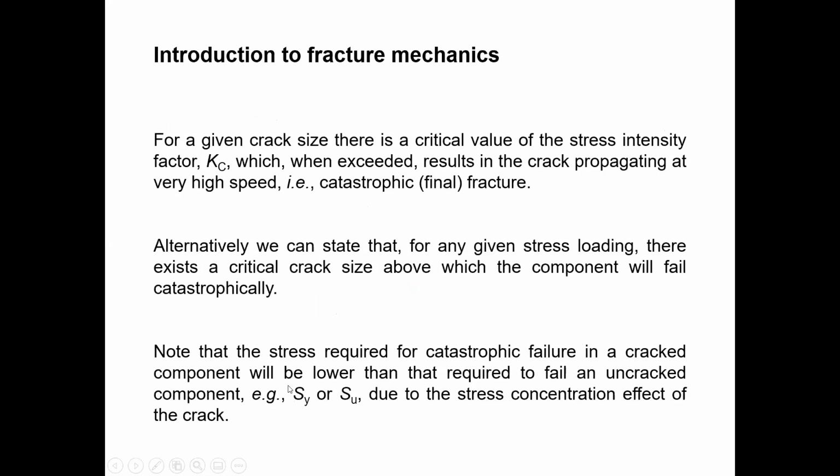So when you introduce the Kc and find the strength, if it is higher than the yield point, or normally we consider the yield point, or the ultimate tensile strength, then it fails catastrophically. According to that, you need to find the Kc. When we deal with the question, you will easily understand that.